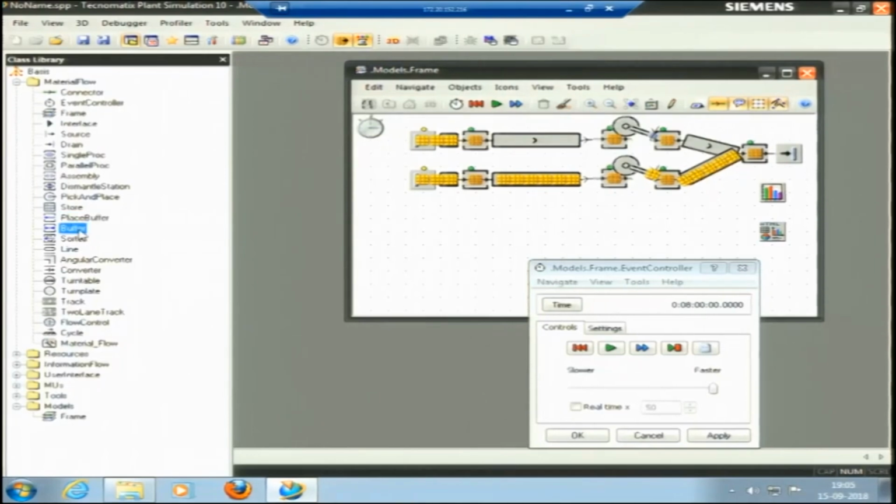So place buffer is a small thing; the big buffer is placed between two plant components for certain purposes. It temporarily holds parts when the following components fail, when the successor is not able to receive the component. The second important function it does is it passes the part on when the preceding components stop working. A buffer with large enough capacity for covering all failures leads to complete decoupling of the plant, and the other attributes as well.